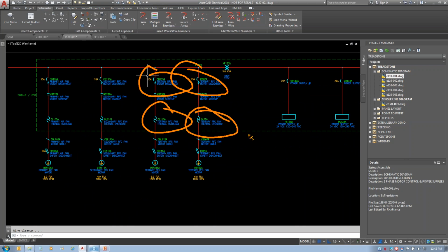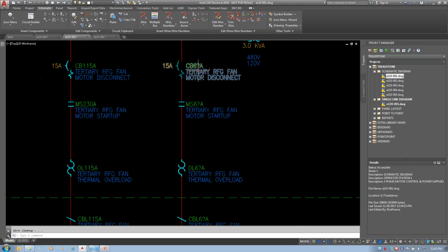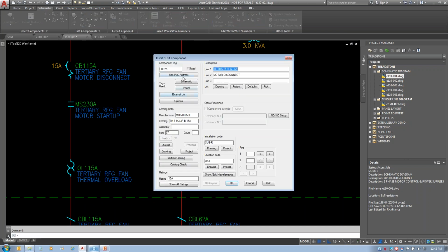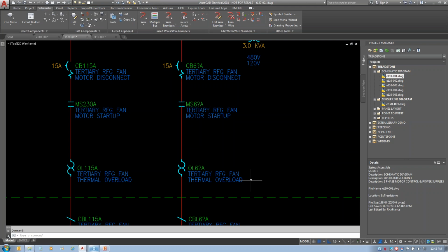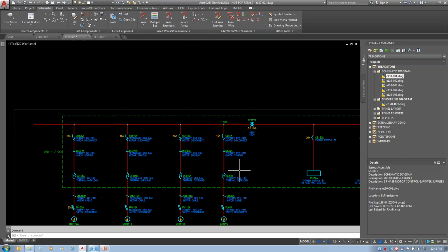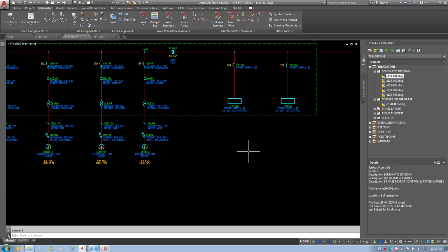These are both the same overload. As long as you retag them, it will break it, but then you're still going to be going through and having to reconnect this stuff up. So I don't know that you actually save any time doing that. So I usually don't bother myself. That's why I just always just read it. Now, I probably would have drawn this one and then copied it over instead of doing them both separate like that. 2 items like that, okay, repeats as fast as copying it. So there's nothing wrong to use copy circuit, though. You just got to watch, make sure you retag them.